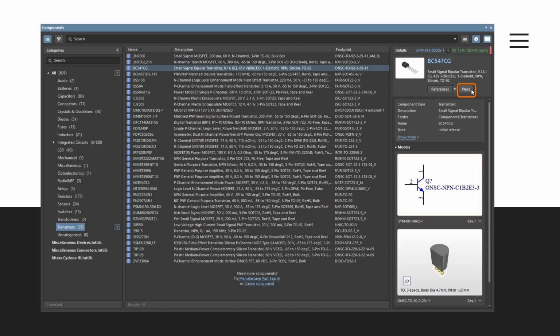After placing the component, another instance of the same component will appear on the cursor. Right-click to drop out of the placement mode. Then, right-click again on the component and select Place from the context menu. The component appears floating on the cursor, position it and click to place.